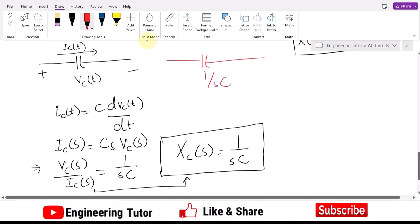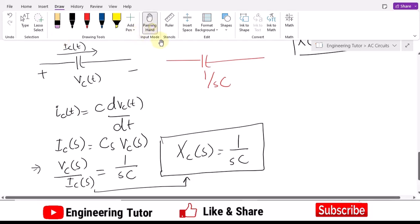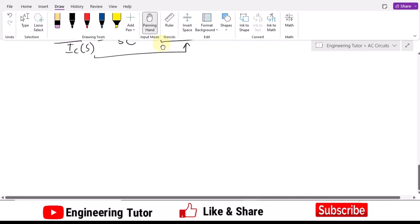So that is a very interesting phenomenon in which any capacitor of capacitance C will be represented by 1 over S C. Similarly, the inductor will be represented by S L. In the same manner, any circuit can be converted into the S domain and analyzed by using the same formulation.